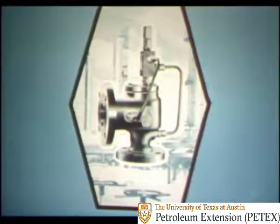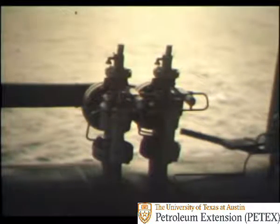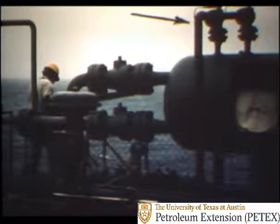The next external feature is the safety relief valve, located on top of the separator. These valves are designed to relieve the pressure when the pressure inside the vessel exceeds a set point, which is always below the design working pressure of the separator vessel. Should the pressure rise to the set pressure of the safety relief valve, the valve opens and releases the gas to a flare line. On most separators, two safety relief valves will be found, with one set at a slightly lower pressure than the other.